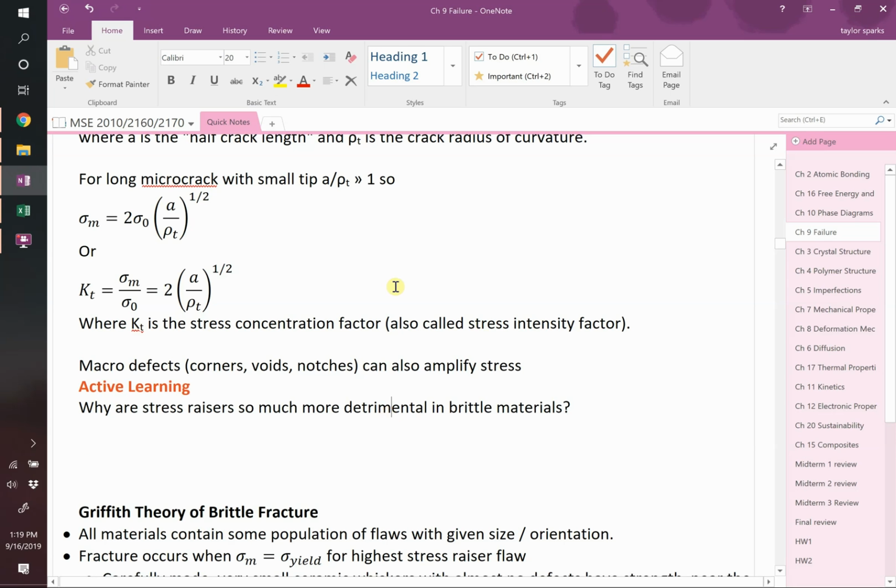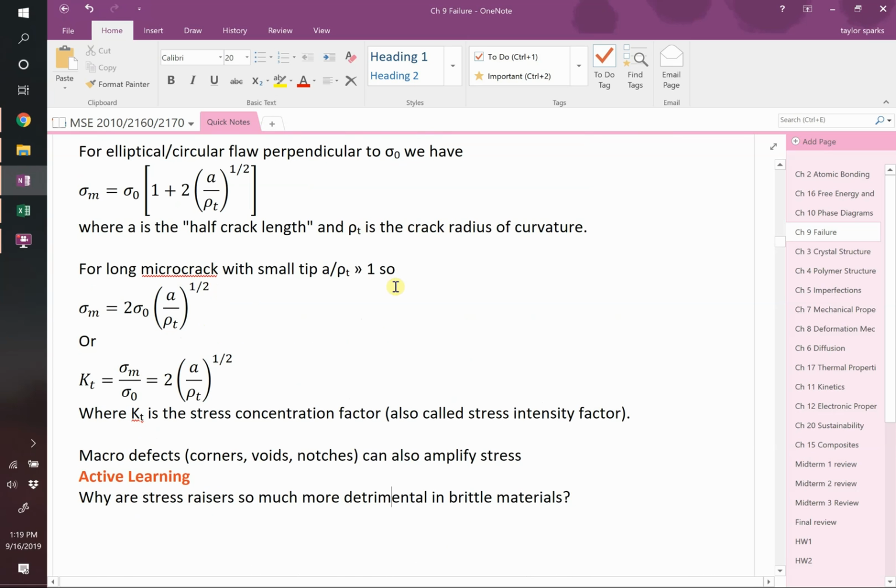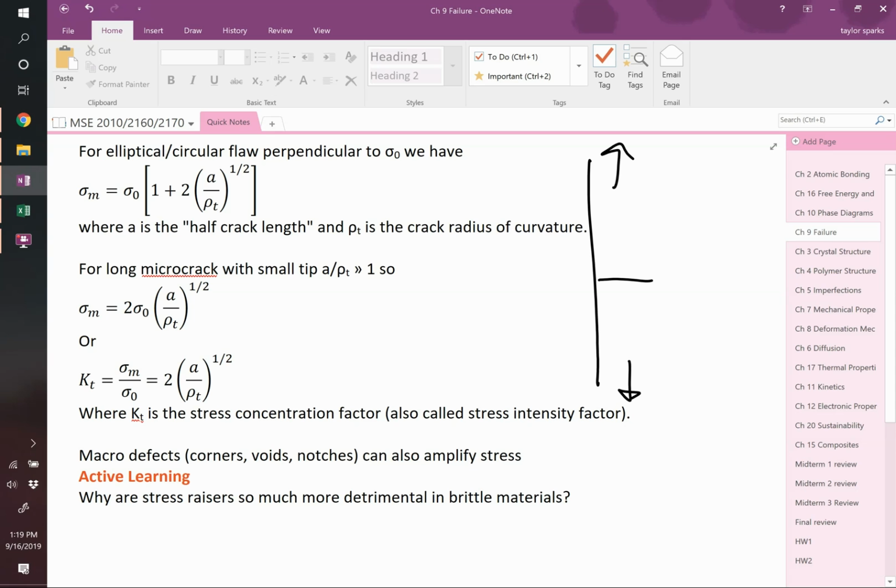Think of what happens. Let's say we take this hairline crack for a minute, okay? You got a material. So that's your material from the outside. It's got a hairline crack. And we're going to pull on this thing, which is going to extend that crack. In a ductile material versus a brittle material, the brittle material is not able to deform. It can't tolerate plastic strain. There's no plastic strain. It's only elastic. So ceramics, you can't bend a plate. Once that crack starts, it just propagates. But in a metal, you can bend it, and what will that crack tip do you think?